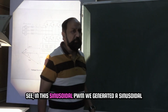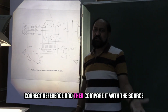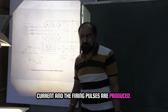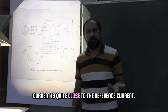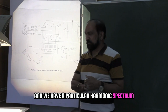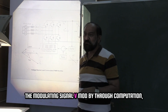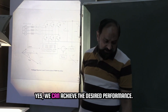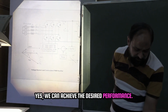In this sinusoidal PWM, we generated a sinusoidal current reference and then compared it with the source current, and the firing pulses are produced. By doing that, we ensure that the source current is quite close to the reference current, and we have a particular harmonic spectrum. In the other one, where we generated the modulating signal V mod through computation, yes, we can achieve the desired performance.